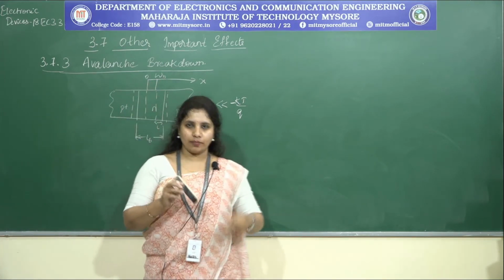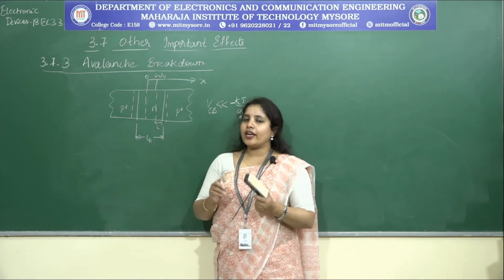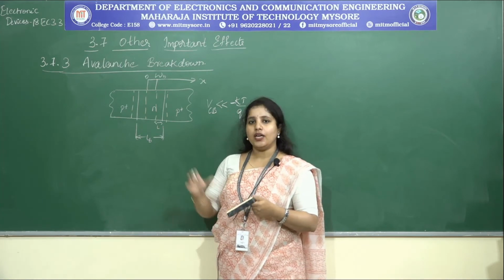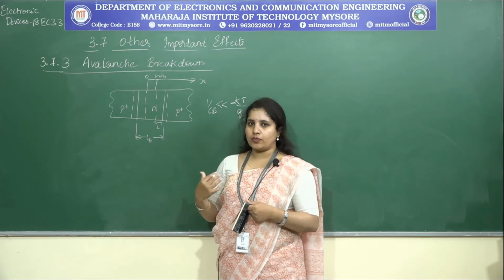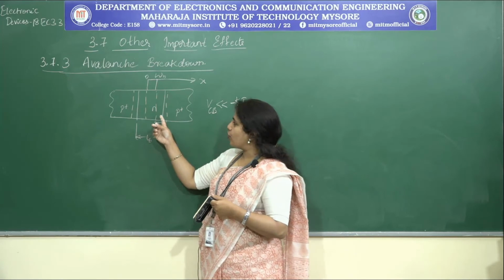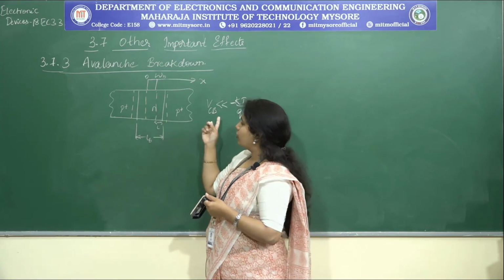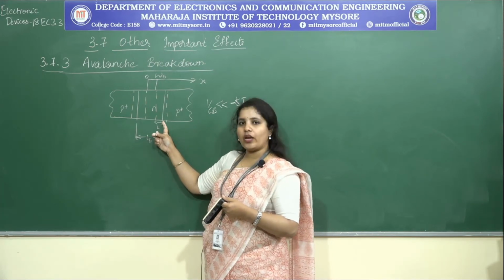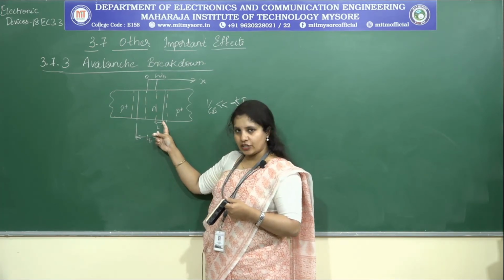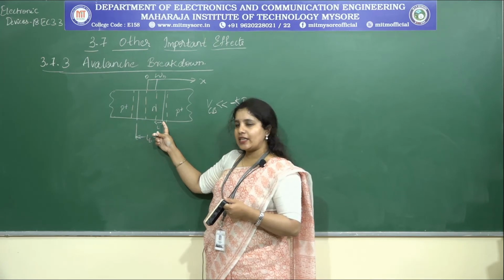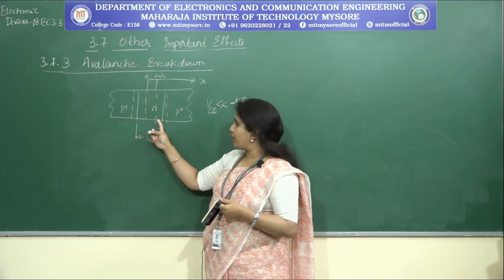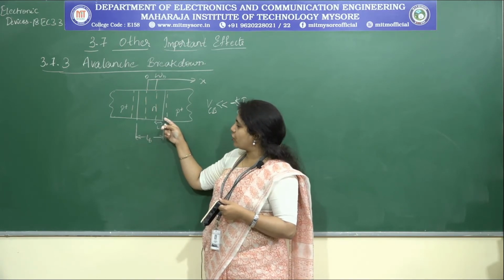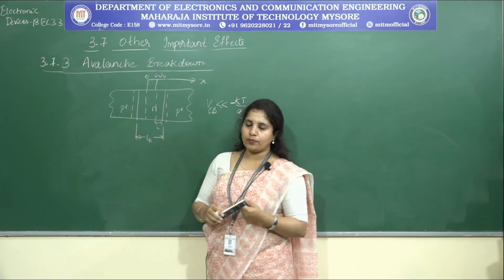Now what is this avalanche breakdown? We have already come across this phenomenon when we considered the diodes, that is the PN junctions. The same phenomenon occurs here as well. That means as I increase the collector base potential at the collector junction, what happens to the reverse bias potential? It tends to increase, which in turn increases the depletion region across the base, which tries to encroach more and more into the base region.